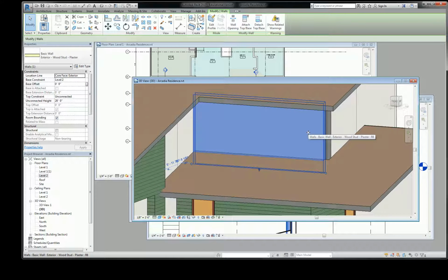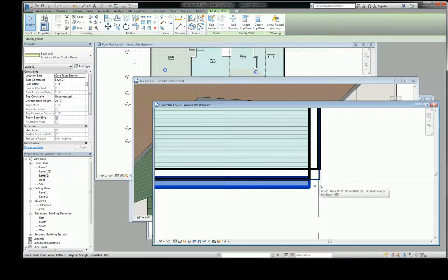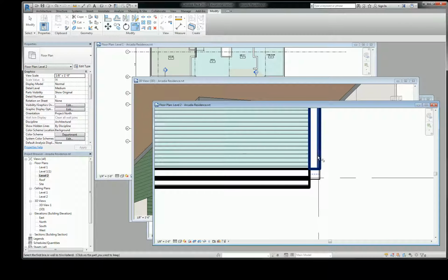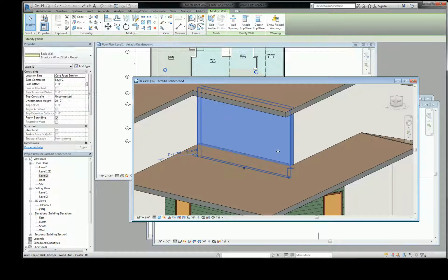And then what you see here is kind of the funny little double wall. You kind of have to clean it up in your second floor condition, because sometimes, when you're doing all these weird, not exactly correct modeling tricks, the connections aren't really right. So what we've got to do is modify with the trim extend corner and make sure this wall is connected to this wall. That's going to clean up that outer corner for you over here. Okay, that's key.